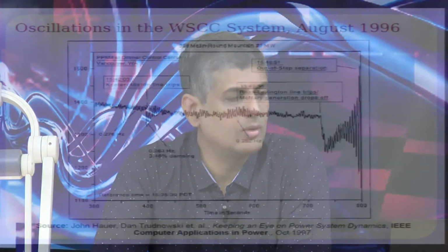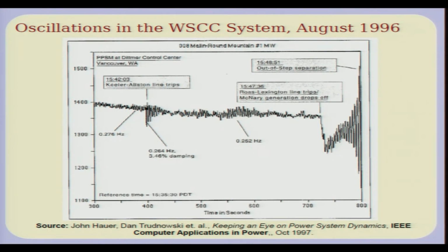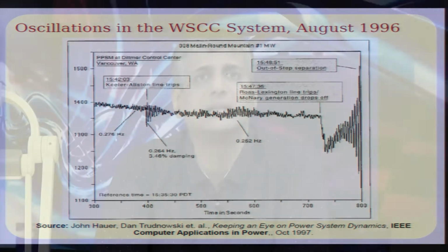So, you can in fact alter the control system in, for example, the excitation system of a generator, or you can modulate the power flow in an HVDC link in a certain manner, so as to damp out these power swings. So, these kind of controllers are called stabilizing controllers, and they are present in the controllable devices in the grid, like the generator excitation system, the HVDC links. If you have got STATCOMs and so on, you can actually modulate them.